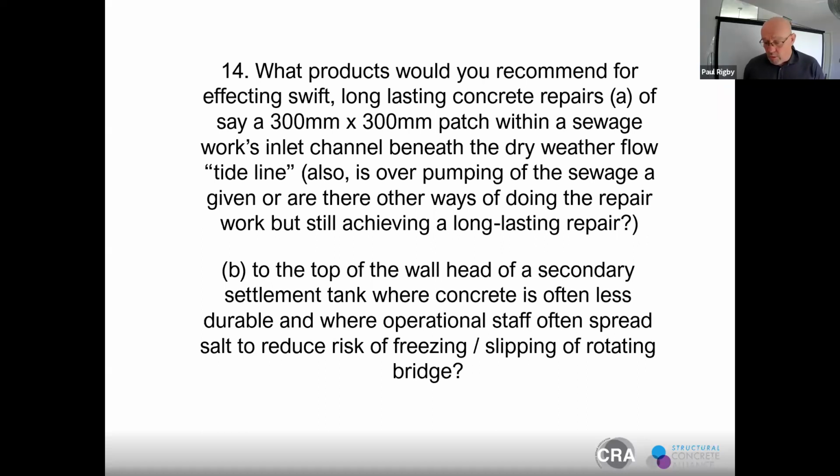From my point of view, you could always look at highly durable materials such as epoxy resins. You could even consider polyesters for small local repairs, but epoxy resins would be good for chemical resistance, though they're very expensive. You could also consider cement-based materials.